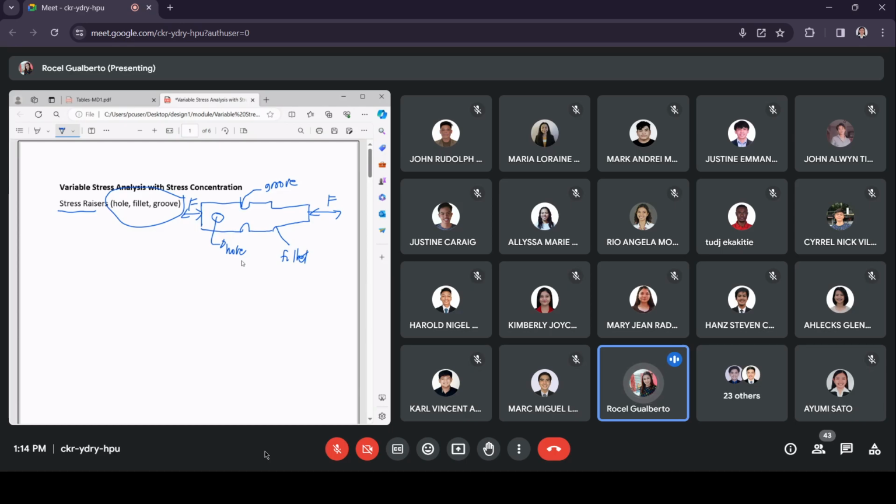But when you say a stress raiser such as the crack or the blowholes, they are really not part of the design. The blowholes are the air that is trapped along the thickness of a glass. You would observe this on our glass bottles. These are not part of the design, but through the process you have come up with those surface discontinuities. So those are not what we mean here by stress concentration.